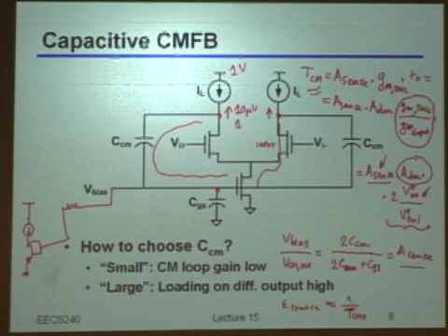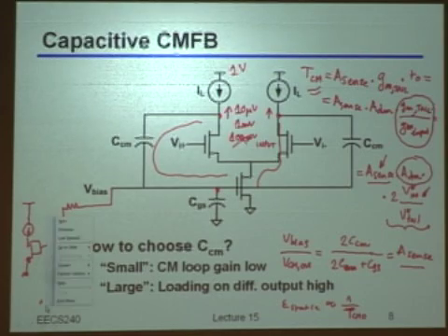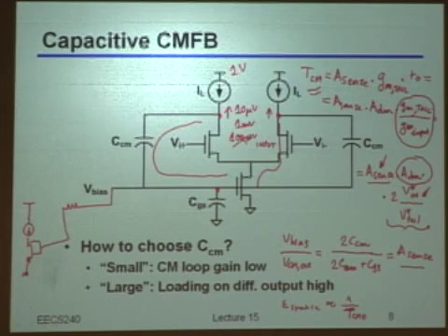Maybe 1 millivolt even. Well, 100 millivolts, I would say, starts to be kind of problematic, right? So you don't want wiggles of 100 millivolts at the common mode with the 1 volt, most probably. That depends on your problem or your specs, of course. But the idea is, even if you are tolerating, or you're saying, okay, I want 1 millivolt, let's say, over 1 volt, that's going to be 10 to the minus 3. We are requiring a loop gain of 1,000, right?